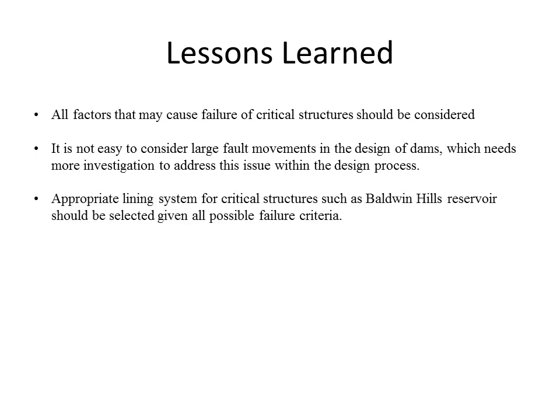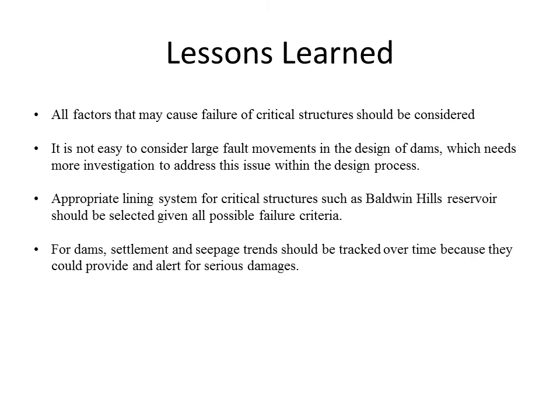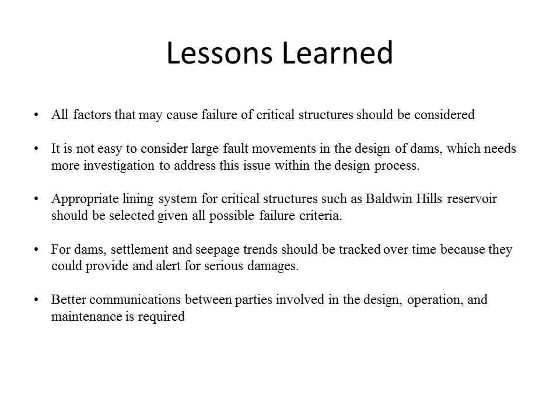An appropriate lining system for critical structures such as Baldwin Hills Reservoir should be selected given all the possible failure criteria. For dams, settlement and seepage should be tracked over time because they could provide an alert for serious damage. Better communication between parties involved in the design, operation, and maintenance is required.